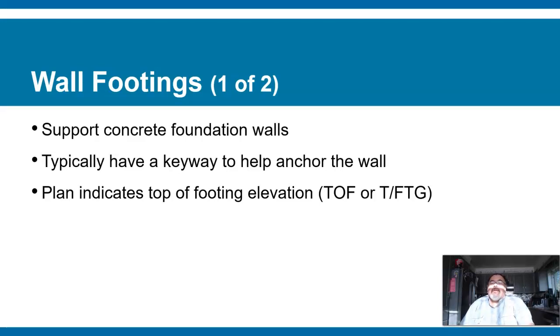And it would be anchored together with anchor steel, so that when you poured the new pour, coming out of the first pour and the second pour, you will have steel. So once you pour into that steel, then the two will be attached, and also the keyway helps keep things stable so they don't move. And I'll explain and I'll show when we see a picture of that.